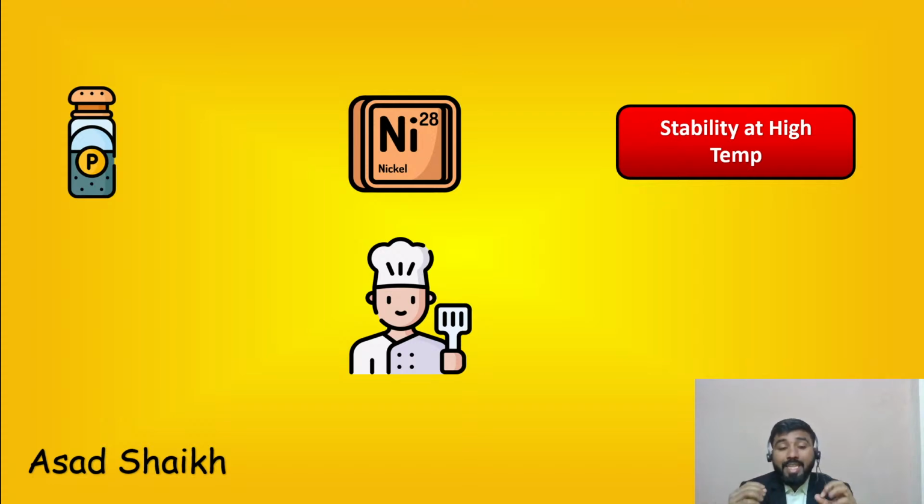That being said, if I ask you right now in the chat as well, you will say that in most applications, especially for instrumentation, you would see SS316. The reason is it has nickel, it has chromium, it has carbon. So it is comparatively hard, it has good corrosion resistance, and because of nickel it has stability at high temperature. So for most applications you will see SS316 being good, but that does not mean every single application.